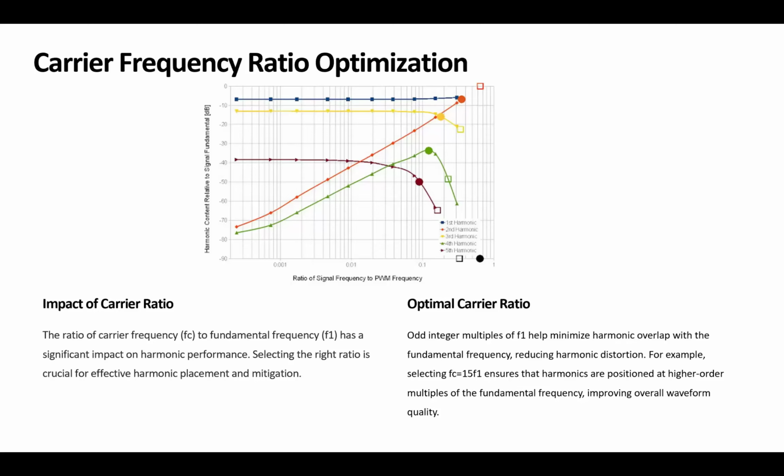Or as we know that the harmonics are going to get lower and lower when the frequency goes higher and higher, one strategy would be let's target the lowest harmonics in perspective of the frequency. So let's target exactly the third component, the fifth component, and the seventh component, or maybe 11th component, those low frequency harmonics that we have.